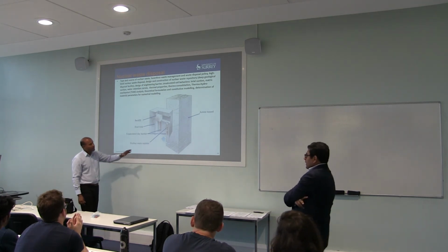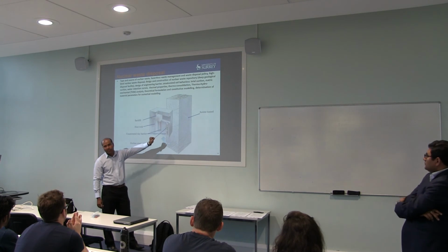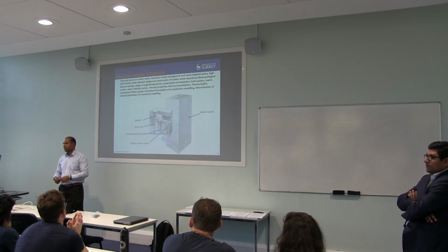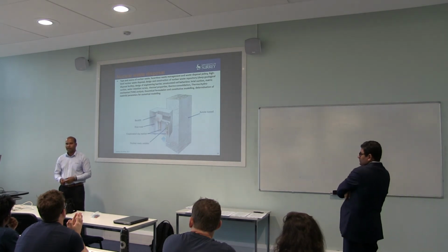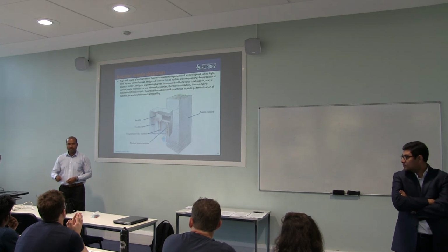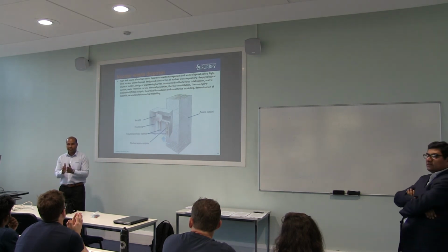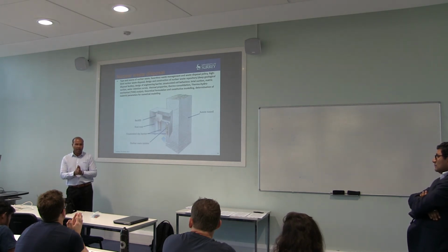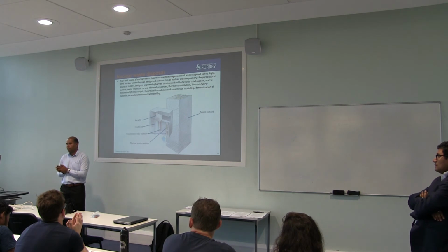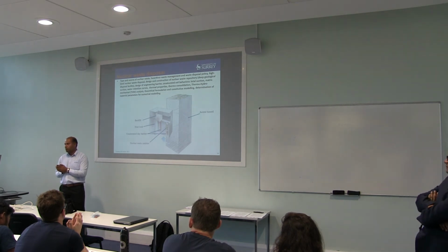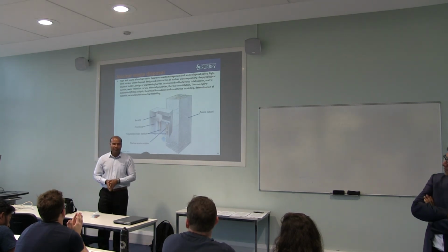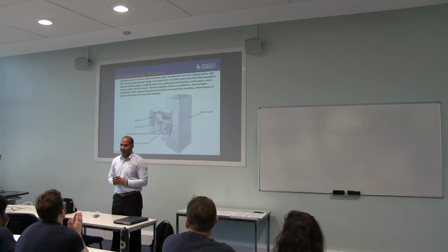So basically this is a clay liner, and it's a swelling clay liner. Clay swells. Clay is also of two types, swelling and non-swelling. When you put water in swelling clay, it will expand. It can expand by almost double or triple, depending upon the type of swelling clay and what minerals are there. If you're building a house on a site, you want to make sure that you don't have swelling clay at that site.